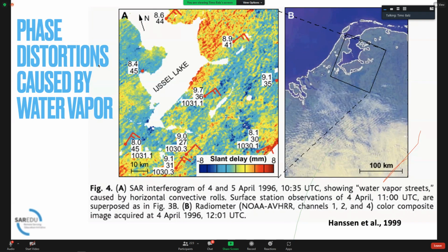So you see on the right side, on the weather image, that is a rather calm weather situation, right? That is not a huge rainstorm or something. It's very calm weather that we have here. But the slant delay is already several millimeters, almost a centimeter. I mean, almost 2 centimeters, which is quite strong. And if you want to measure in millimeters, that can already be too much.